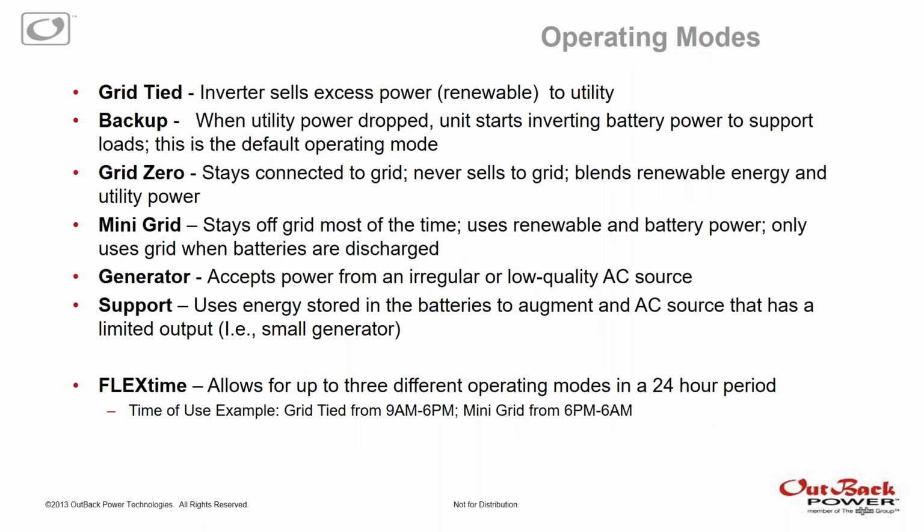So next thing we're going to talk a little bit about, now that we have hopefully a better understanding of what a grid tie plus battery backup system is and what an off-grid power system would look like, is going into some of the operating modes that OutBack has that helps make it a little easier for people to get up and running and for the inverter to do the job that they need it to do. The default mode for all of our OutBack equipment is our backup mode, and this would be the right application for a grid tie battery backup system.